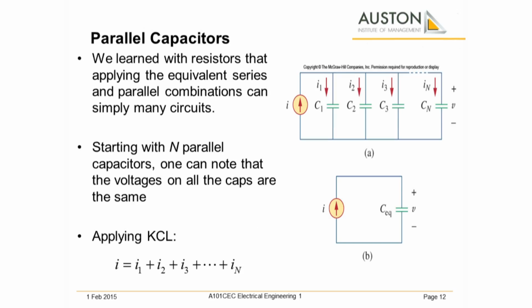When we discussed resistors, we talked about series and parallel connections. We can have the same in capacitors. When we connect capacitors in parallel, in effect, we are increasing the surface area of the plates. So again, what happens when the surface area increases? The capacitance increases.